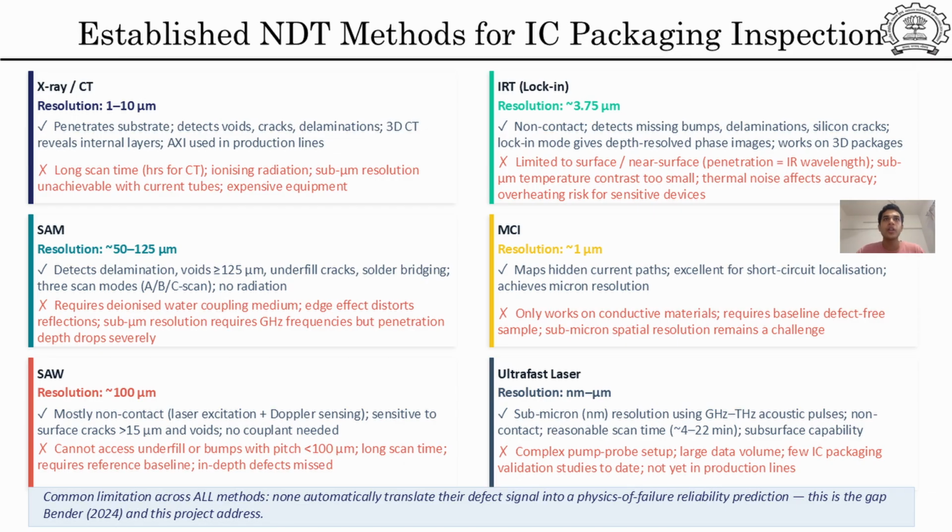SAW. Surface acoustic waves, mostly non-contact, using laser excitation and Doppler sensing. It is sensitive to cracks over 15 micrometers with no couplant needed. However, it cannot access underfill or bumps with pitch under 100 micrometers and requires a reference baseline.